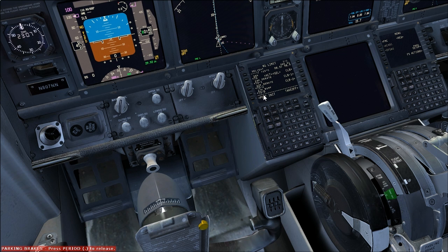And one limit, we're not going to be using this, any derates. This would be if you have a noise abatement procedure at nighttime, but you don't need to use that. And then flaps 5. And then let's get our trim. That's our trim, we're going to be entering that in a little bit.